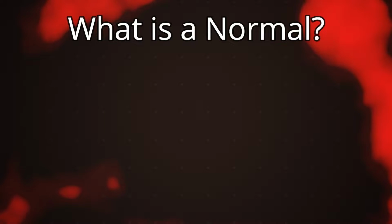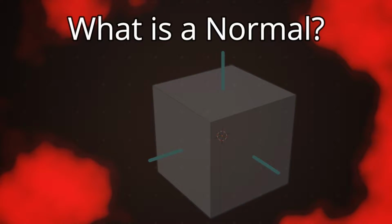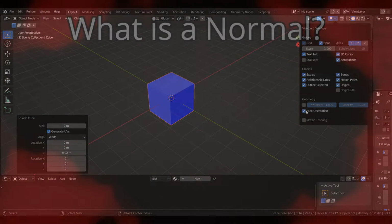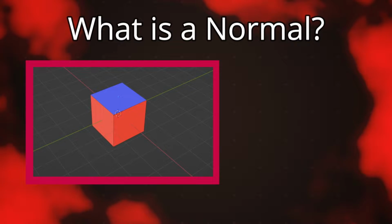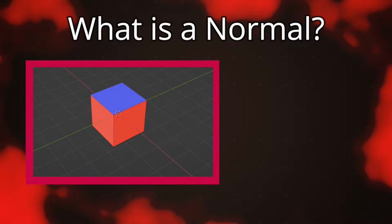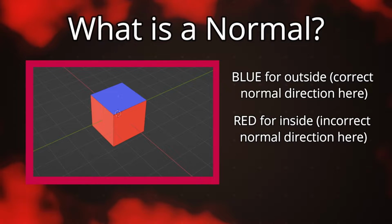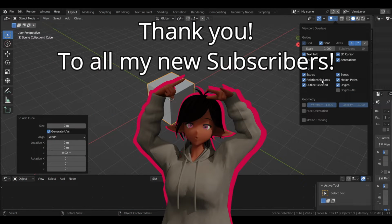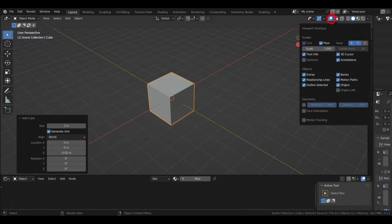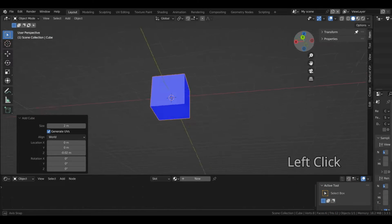If the normals are facing outside, like they should be, they will be represented with a blue line or a blue face. In our 3D viewport, if we want to set up the ability to see our normals, the first way is to use a colorway of seeing our normals, where blue will mean that the normals are facing outside and red will mean they're facing inside. On this cube, we want all the normals to be facing outside, since we're seeing the outside of the cube. So under my overlay tab, these two circles, there's a drop down arrow, and underneath a left click face orientation. And now you can see by default, all the faces are blue.